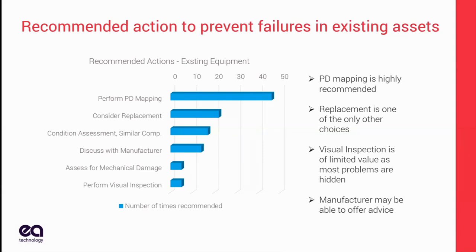You want to look at the condition of similar systems, similar cables, similar terminations. If I'm having a problem everywhere on the same type of termination, I can start doing some asset management and looking at where I've got those terminations. Again, the manufacturer is one of your best allies, and visual inspections of terminations will show that surface discharge. So that's a really good thing to look for.